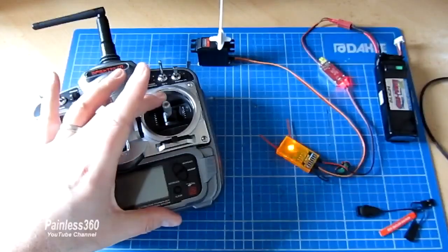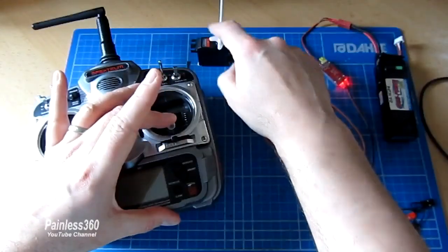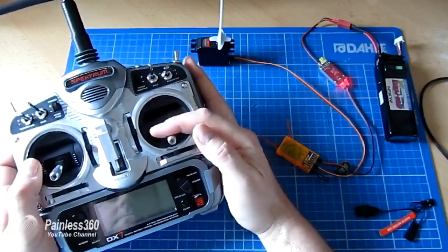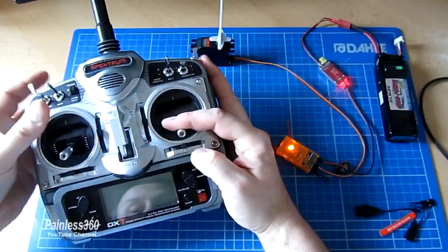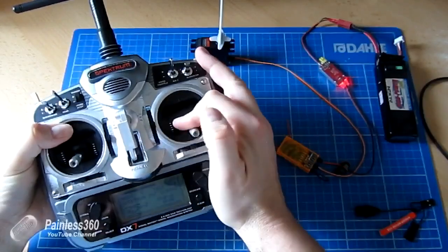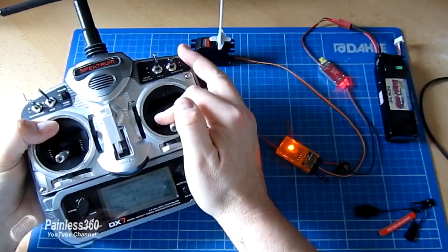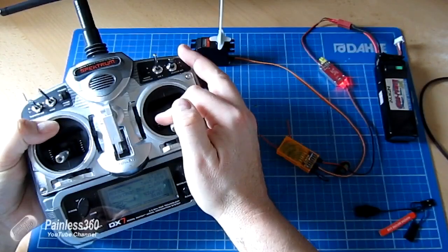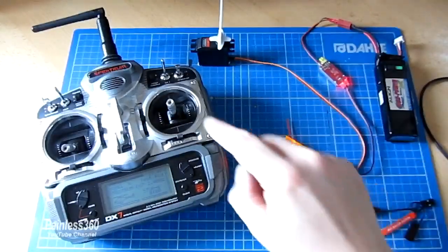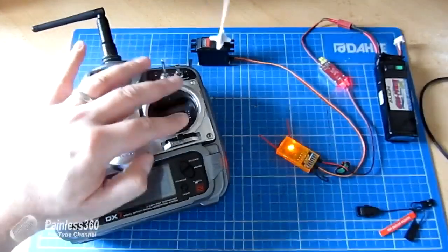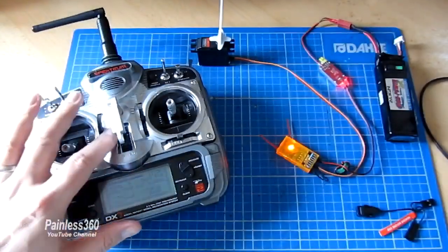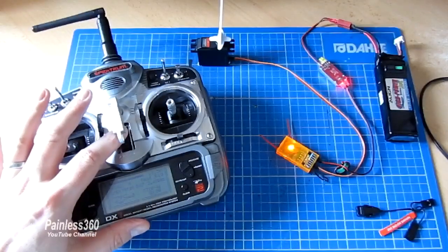This time I'm going to bind it with a channel that runs the servo at this low position. So it's a little bit tricky, but I'm going to hold that stick in its lowest position. I'm going to press the button at the back that will start the bind, and I'm going to turn the radio on. Let me hold it all until the bind happens, and then let go. Now we have it bound again, and we have control of our servo, but this time watch what happens to the servo when I turn off the radio.